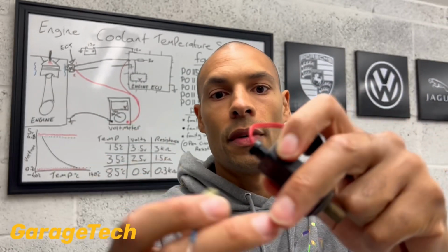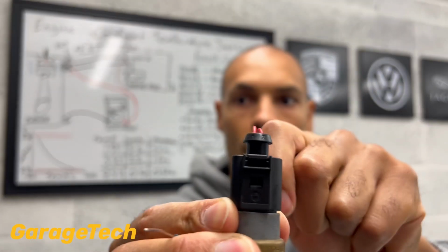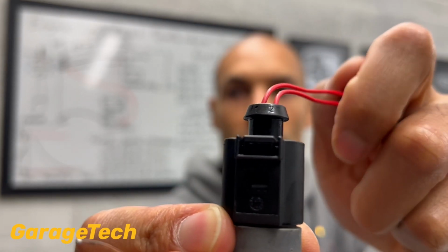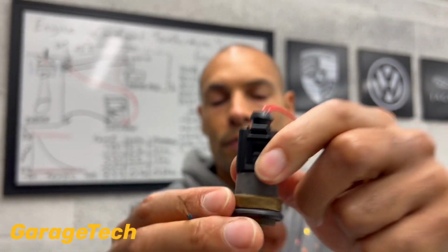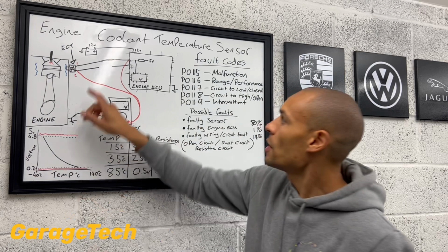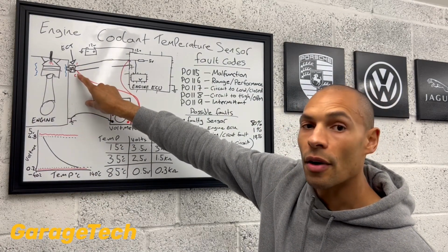And then obviously if you can just about see, I don't know whether it'll go into focus, but it does say on there there's a pin 1 and pin 2. So if you consult your wiring diagram, you'll know which pin you're actually in. So that's a good way to do it. As I mentioned, you go to pin 1, you're probably going to get 5 volts. Go to pin 2, you're going to get 5 volts.